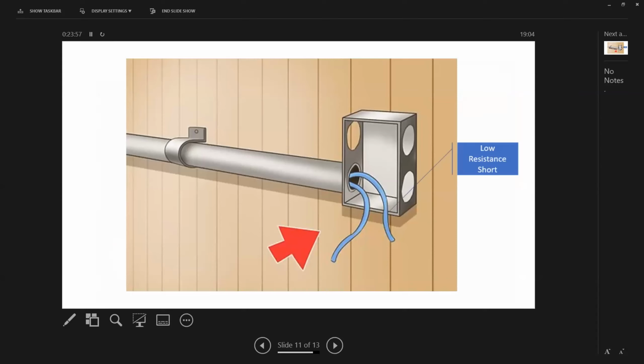And they had a low resistance short caused by one of those wires being right behind the mounting screw for the front plate, penetrated by the tip of that screw and making a high resistance or low resistance, depending upon how you judge those, a short circuit, but not a complete short at that point. Not enough to blow a circuit breaker, but it was enough to pull about 8 amps out of that wire and shove it back through the green wire grounding system on the conduit. So the conduit itself was conducting about 8 amps of current back along that pipe behind all those computer terminals.